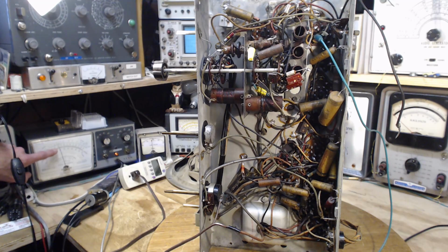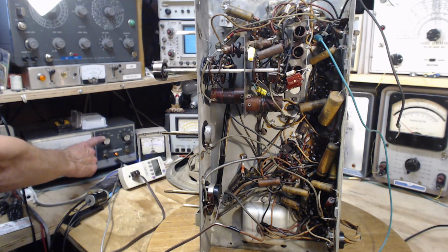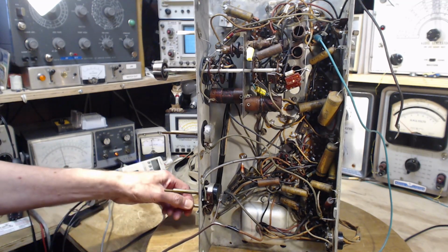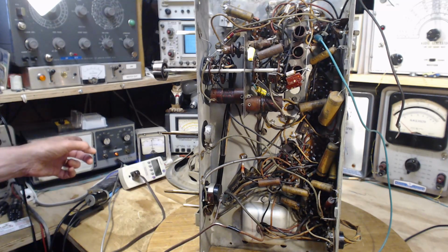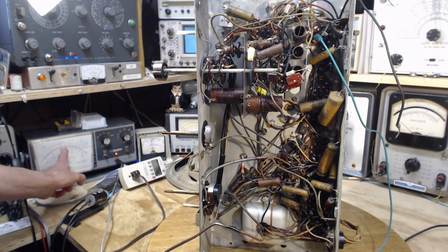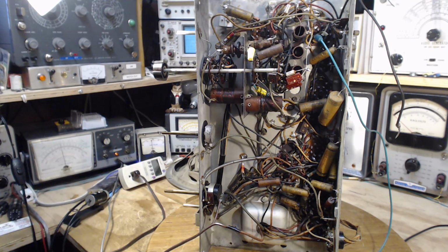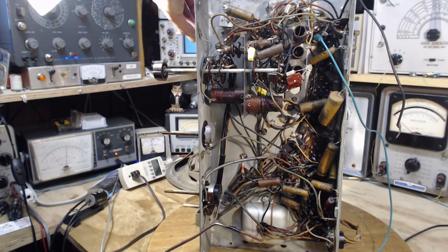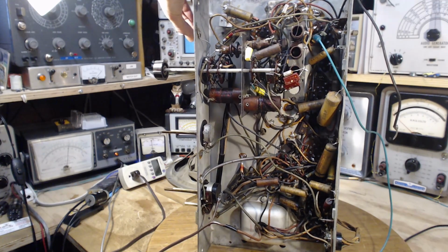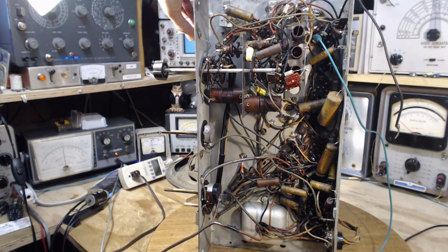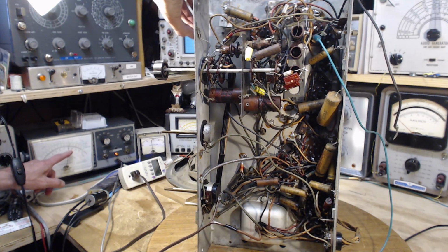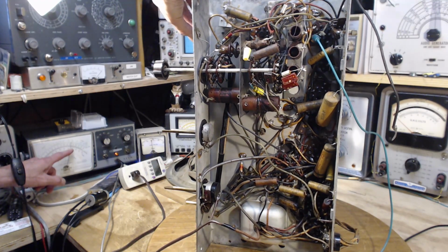So here we are, negative voltage. This is on the negative setting, so upscale reading is actually negative. That's what we expect on a grid. I don't need to listen to that. This is the 15 volt scale, so it's around 7 volts. We're on the broadcast band. I'll tune the radio. Ever wonder why your radio's louder at one end than the other? Yikes, what was that? You can see the local oscillator strength is going up and down here a little bit, but the radio goes quiet way at the top here.